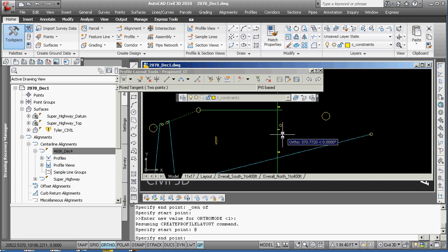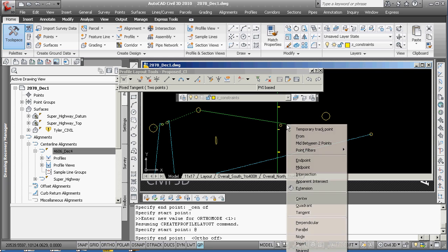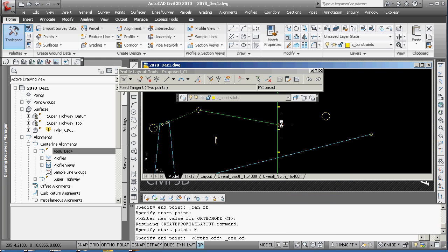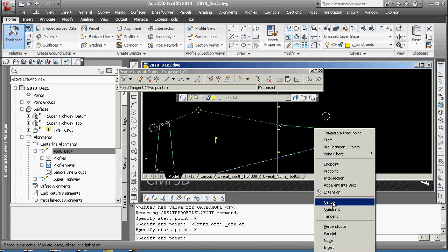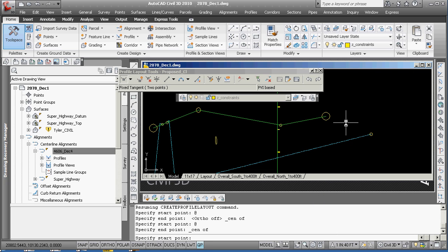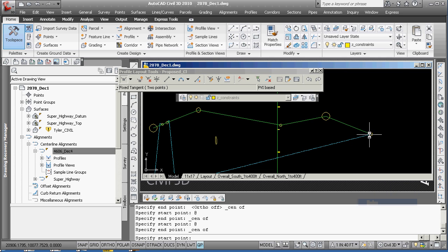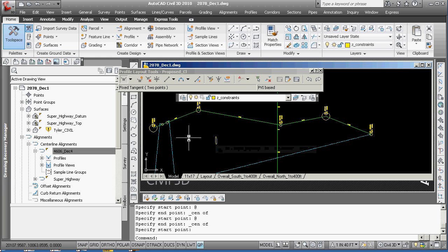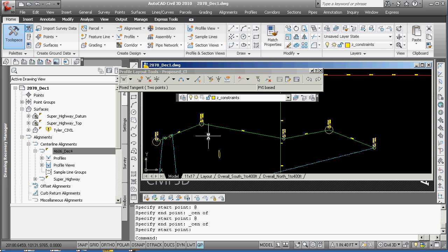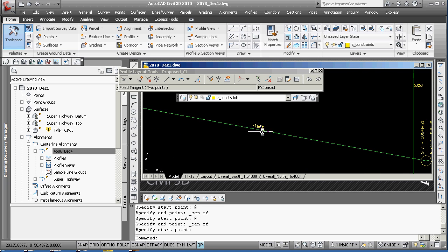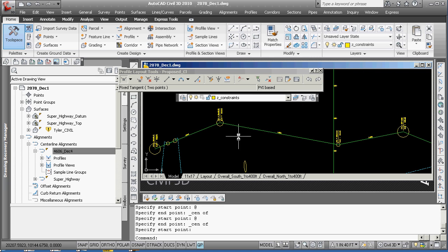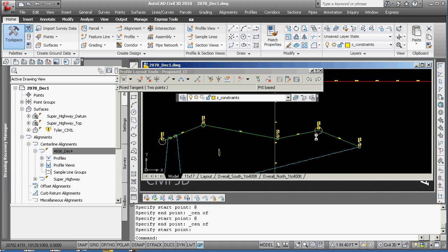And so as I go here, I'm going to turn off the ortho. You say at for the beginning and then to the center. And then again you say at. I don't know why it's set up that way. It's for drafting short tangents that are not connected, which doesn't make a lot of sense in most projects, but it can make sense in many. So now you've got that designed. The next step is to run your vertical curves through, and so you want to double check that your grades are within normal. You're going to have some design buttons to hit soon.